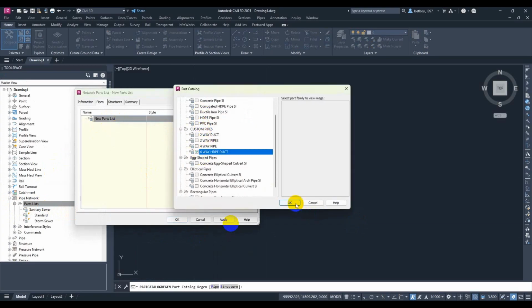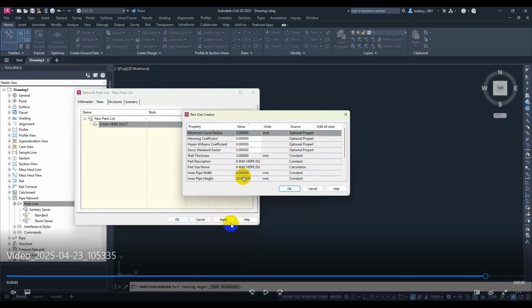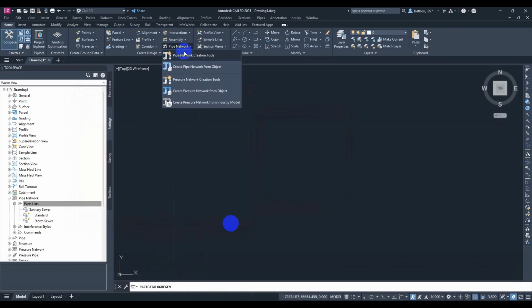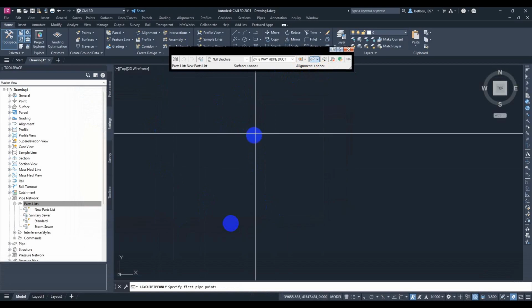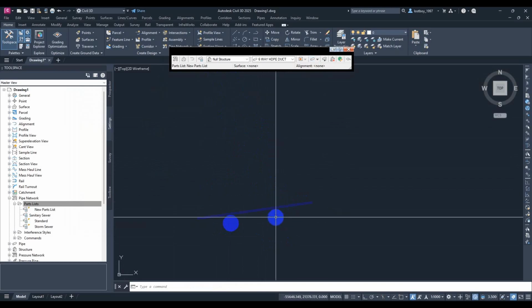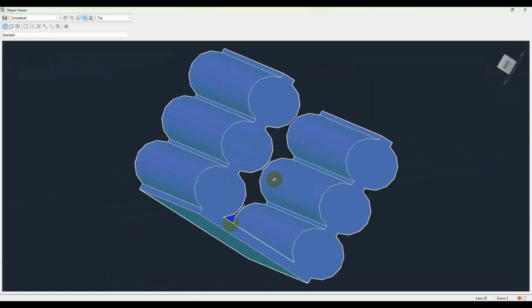Okay. At the side, you see now the size. This is the mistake I spoke about. The size, we didn't change the size in edit values, we changed it in the model parameter. So it will not take the model parameter values. I have to change also in the edit values to make it take the dimension I want. So you will see how the pipe will come out. Yes, see, it's getting the wrong dimensions.